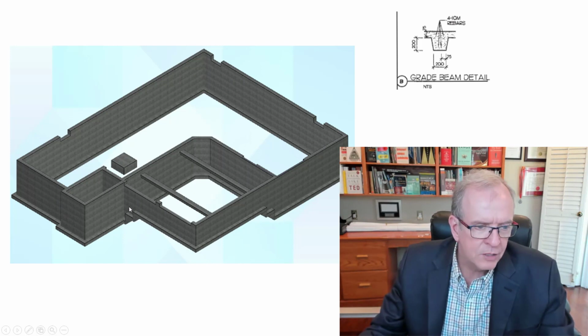You can't just excavate straight to here. If you did, then what would happen is when you put the footing here, it would be on disturbed soil.